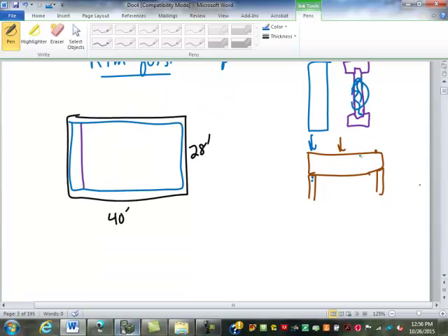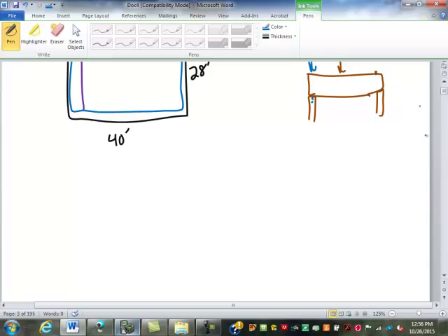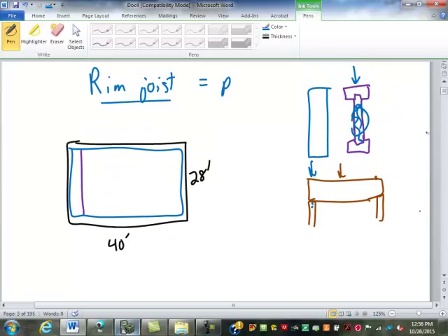Personally, if there's the budget there, I'd go with 2x3 trusses, frame trusses, because then you've got space for all your mechanicals and stuff. You don't have to drill holes through webs. Otherwise, it's all TGIs. But anyway, so if we're doing TGIs, your rim joist is just going to be your perimeter.